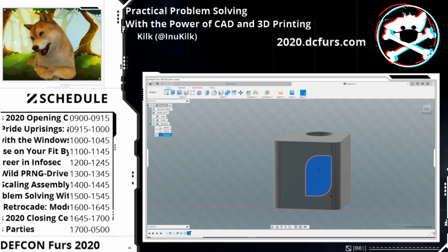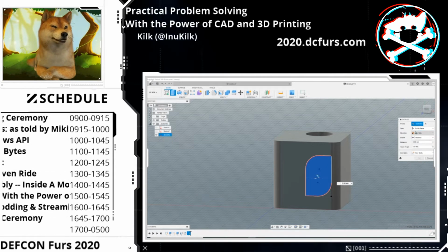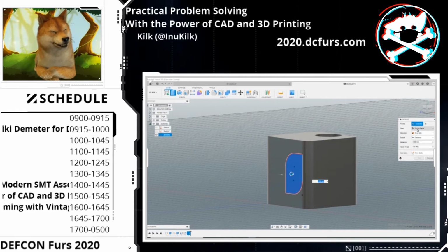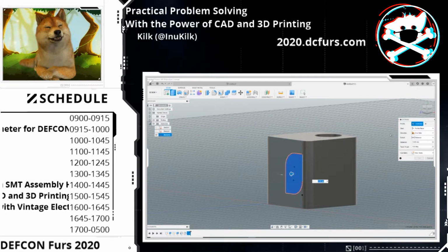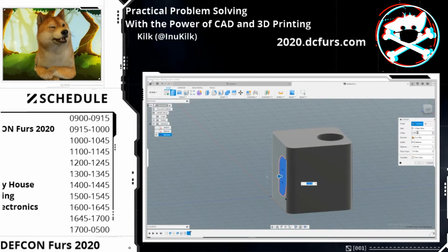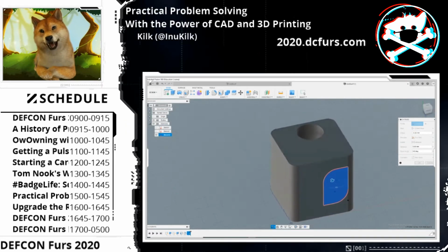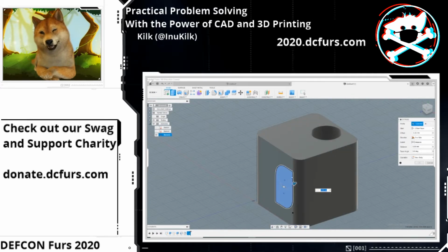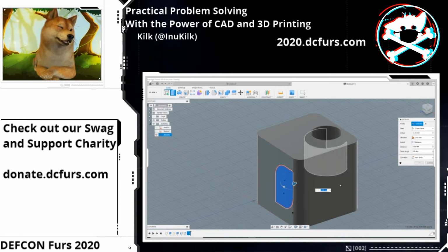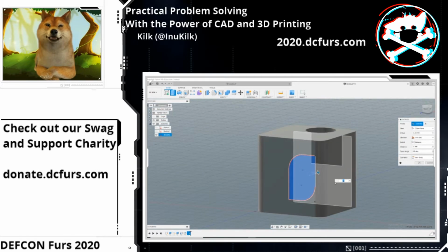So right here, we're going to do an extrusion. Here's another thing. When we're doing the start for the extrusion, see where it says start? It's going to start directly from the sketch. But if we do offset plane, we can do an offset. Let's do -5. So it's going to make a copy of this and move it -5 in the space. And what we can do now is do a -5, right? So now it's going to do an extruded cut that is -5 inside.